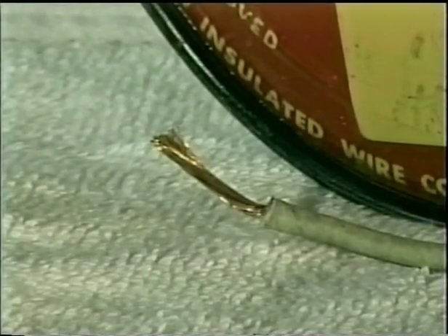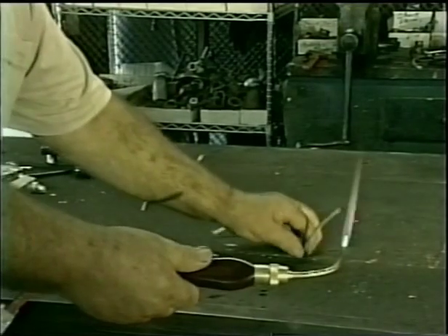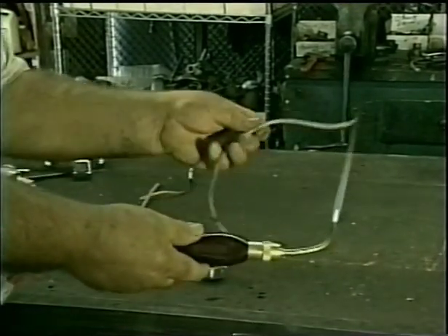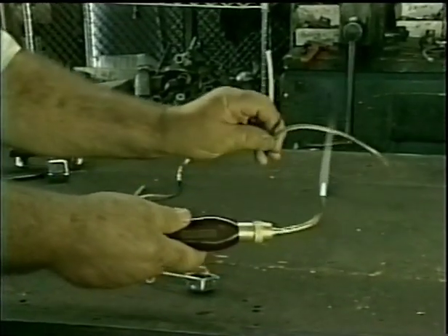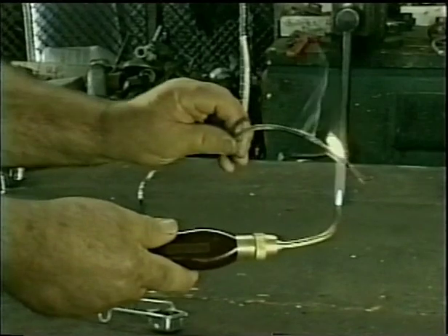In this demonstration, we will expose a fireproof electrical wire to flame. Notice that the wire is covered with a thick, flexible sheathing. During the burning process, most of the covering is burned away. The fine white fibrous material left is the asbestos lining. Asbestos minerals will not burn. They will, however, glassify at around 2000 degrees Fahrenheit.